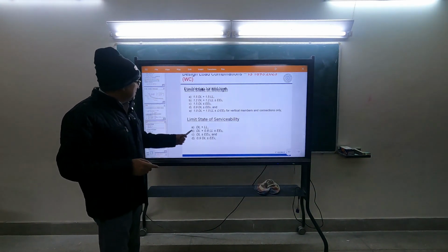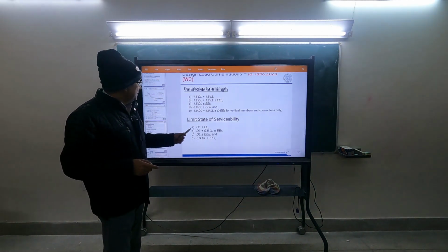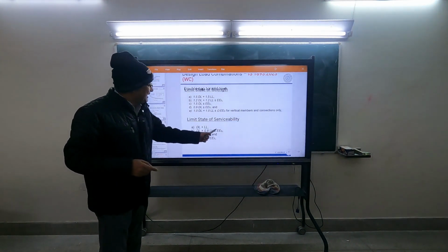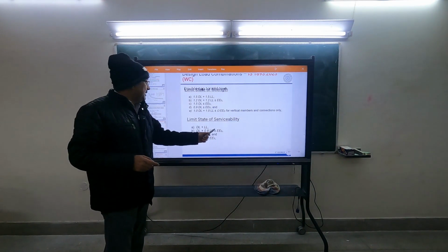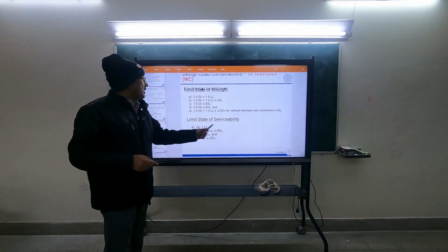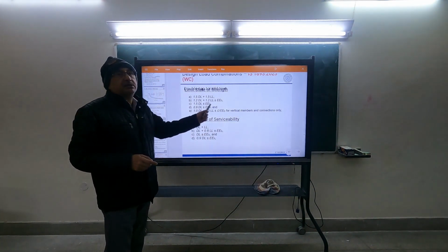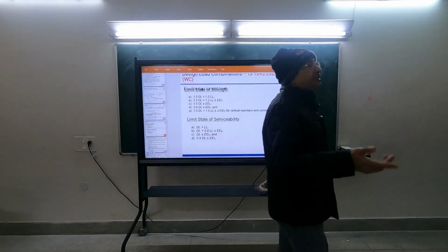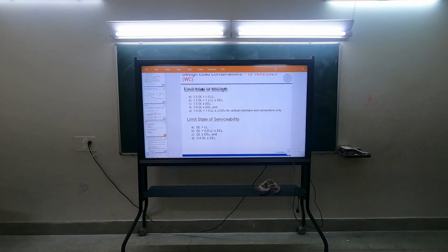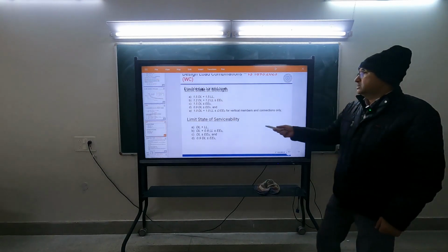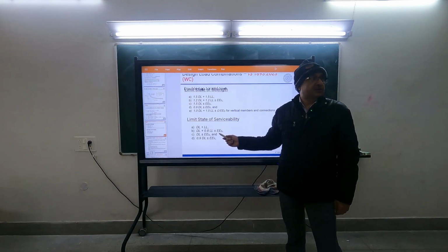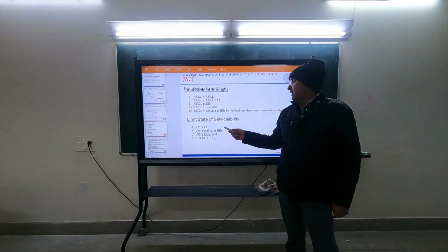And in the serviceability condition, this is dead load plus EES, EED and EES. So serviceability earthquake, here it is design level earthquake. And these have been differentiated by return period. So rather than using an A factor, this is simply being taken for a return period. Serviceability earthquake is directly considered here.